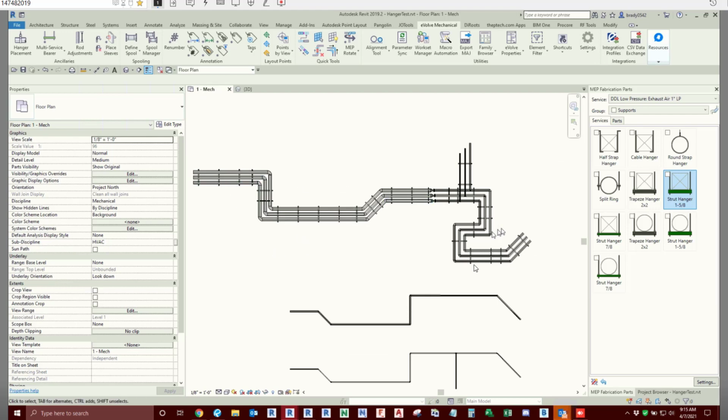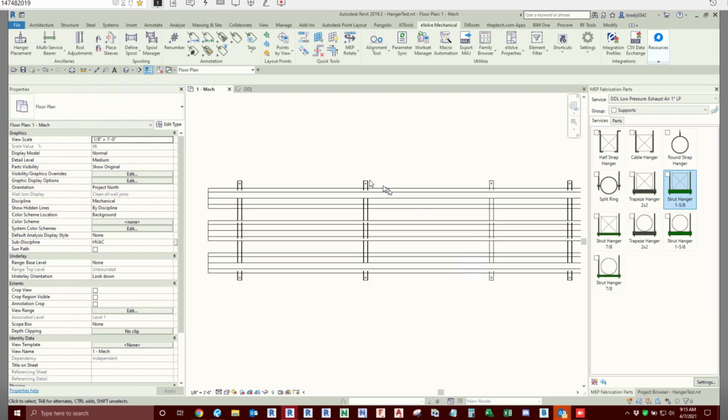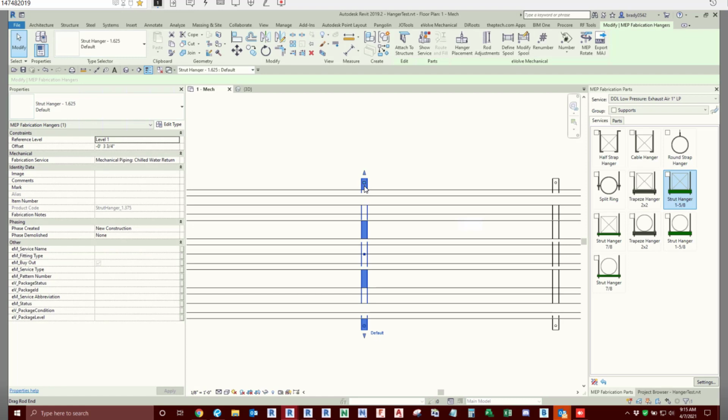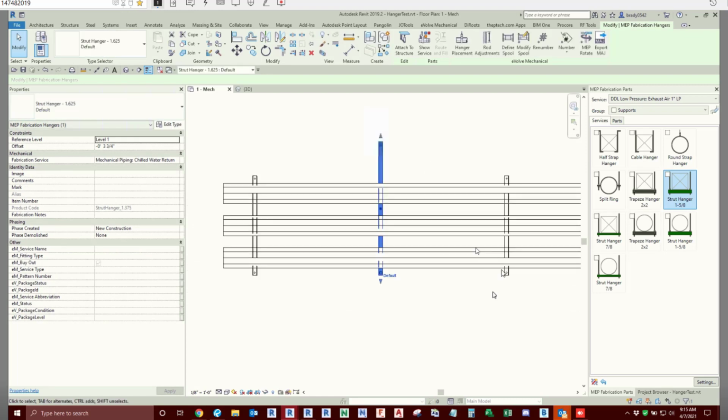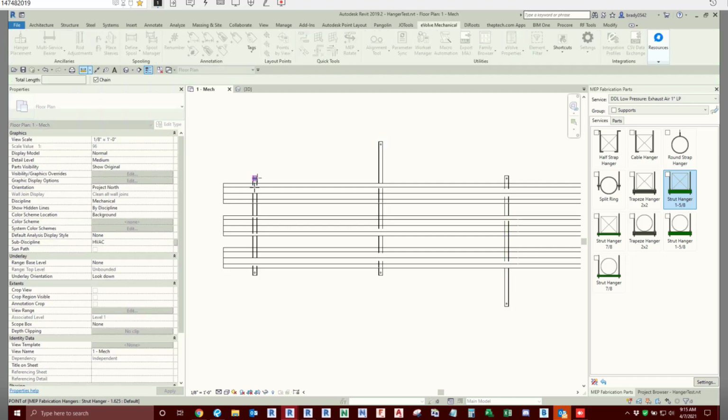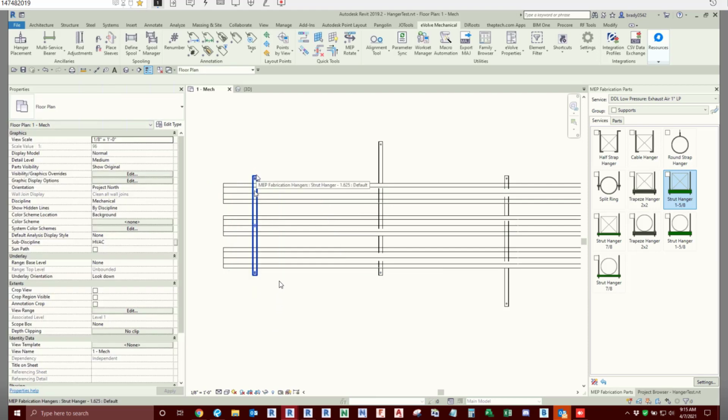But anyway, that is the multi-service hanger. Now, if this is something that comes up with strut a lot, getting into odd length angles, if we go measure this, it also does a very good job at giving you nice round numbers for your hanger placement, and also round numbers for the ends of the struts.